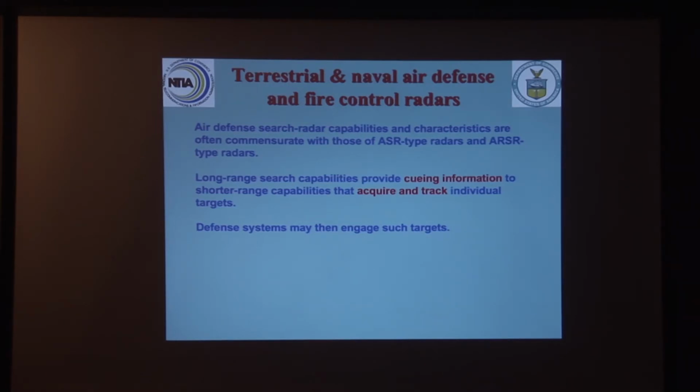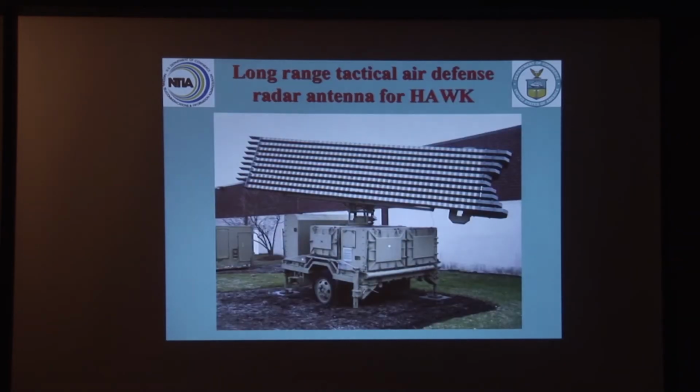You can get literally burned either way. But the bottom line is that with long-range search combined with acquisition and track capabilities, you can operate an air defense system. Historically, the search, the acquisition, and track were broken up into separate radar units. Nowadays, a lot of the time, these functions are all combined into one single radar unit that does a lot of electronic switching and multi-mode operation.